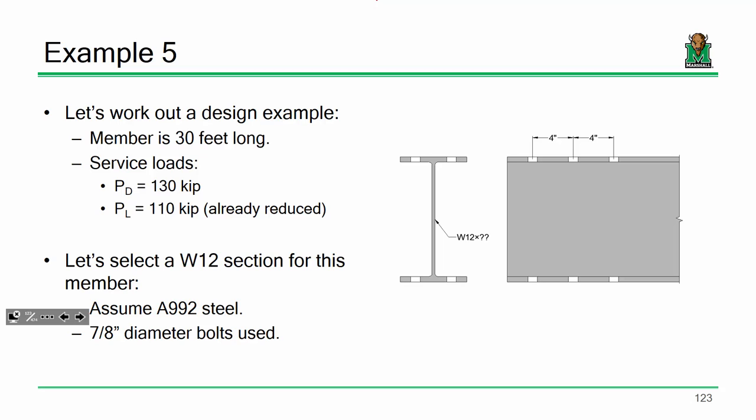If you haven't already tabbed it, that was one of the ones that we indicated you ought to tab. You'll notice that for W shapes, by and large, the preferred material specification is A992. Everybody see that? You'll note that by the black cell in the table, because you've got gray ones, white ones, and black ones. So what's the preferred material spec for a W shape?